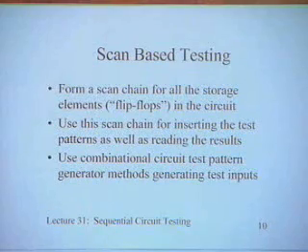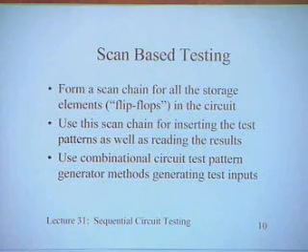You can use that to generate the test inputs required for any combinational circuit. What do you use the flip flops for? Of course, there are sequential circuits and there are flip flops. One thing is you have to make sure that each of the flip flops is working fine. The only thing that we try to ensure there is that each flip flop can be set to 0 and set to 1, like it actually toggles, so it is possible for the flip flop to take a value of 0 as well as a value of 1. This is ensured in some manner. We will say how it is done.